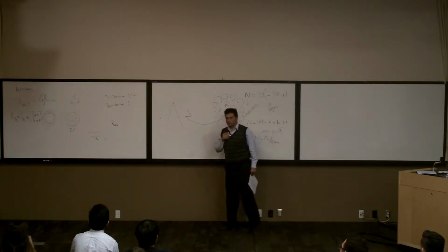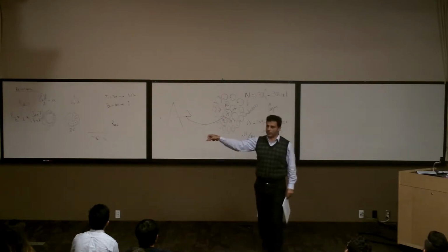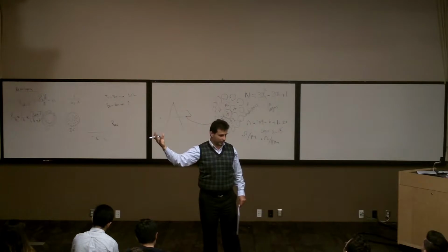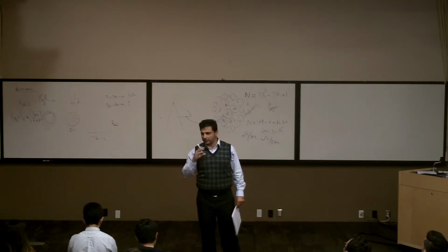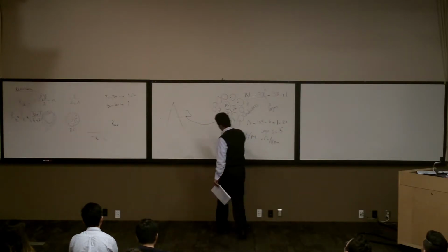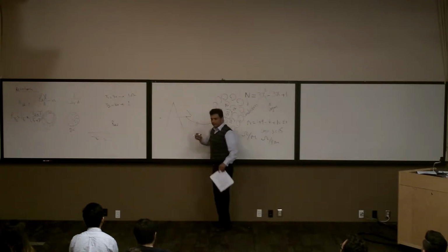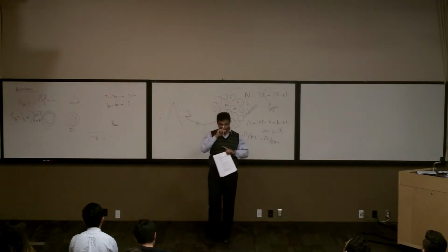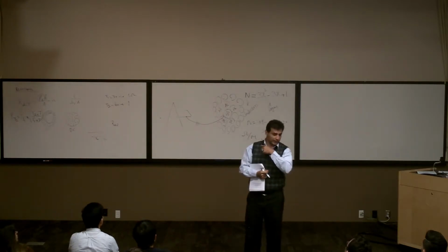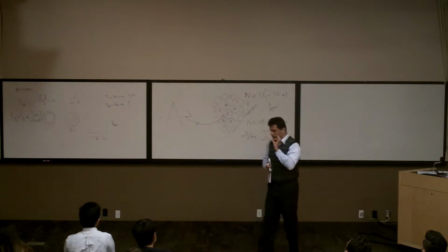Remember we talked about the corona, right? What was corona? On days like today, when there is humidity, we have water in the air, and if there is a high voltage transmission line, you really start to have some current going outside through the air. And tonight, if you can find a high voltage transmission line somewhere, you can go look at this one. You should be able to see the corona. There is like a blue light around the wire.